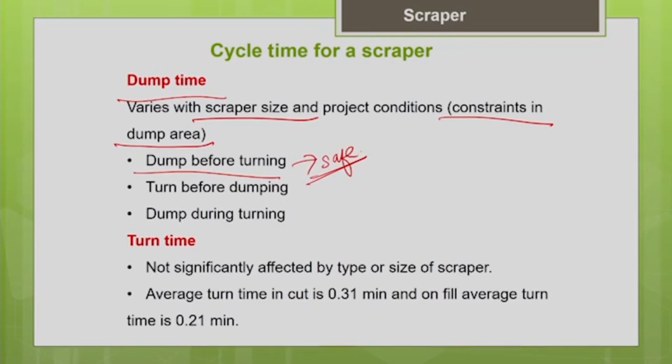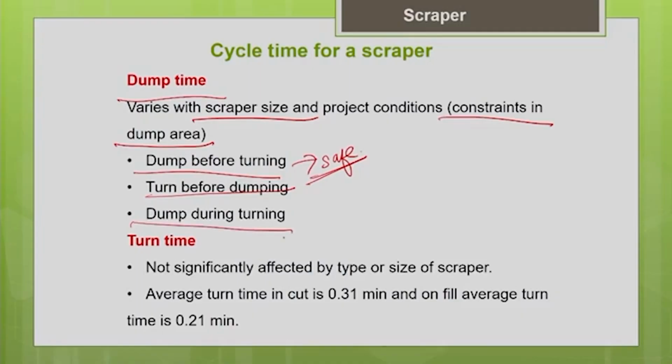In some cases, depending upon your project site, you can see that it will turn before dumping. That means it is turning in a loaded condition. This is relatively unsafe for the scraper. Sometimes you can see that your scraper will do the turning and the dumping together. That will actually increase your dumping time. So, there are different ways to do it.